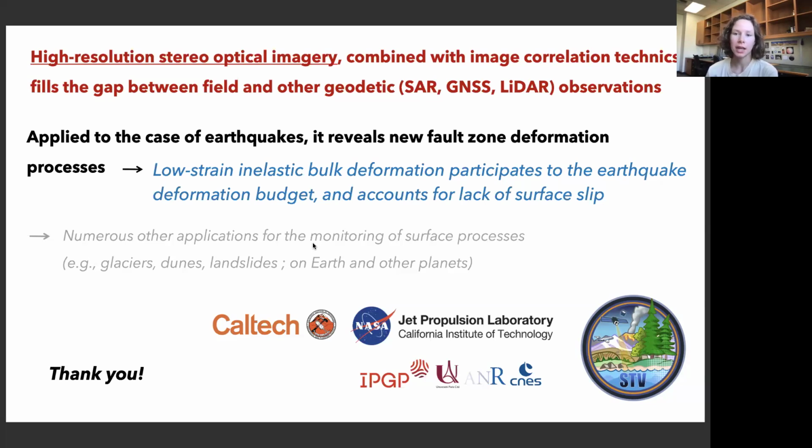And overall, what I would say is that the shear modulus can be very small at the surface, down to a few GPa, and it evolves non-linearly towards depth. And this is very dependent on the material. Some materials have an evolution of several 100%, and some others within 20 to 30% of their shear modulus. So it will definitely impact, but especially impact the scale of that yielding area.